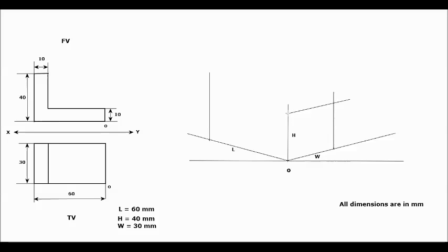Through the same point, the height marking, you have to draw a line parallel to the 30-degree inclined line on the left side, and the intersection will give you the new points. Through both those points you have to draw lines parallel to your isometric lines so that you can complete the box as we did in the last example.